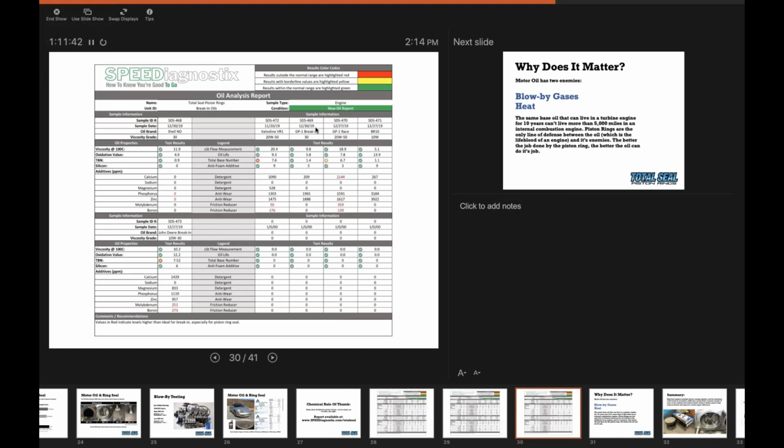That's kind of what you're doing with break-in oil: you've got a little more ZDP because that surface is still fresh. It's clean, it's new, which means there's no anti-wear film on it. So that higher level of ZDP initially for break-in with low detergent allows that primer effect, right? You're getting the anti-wear film established on those parts, then you're just maintaining it afterwards.